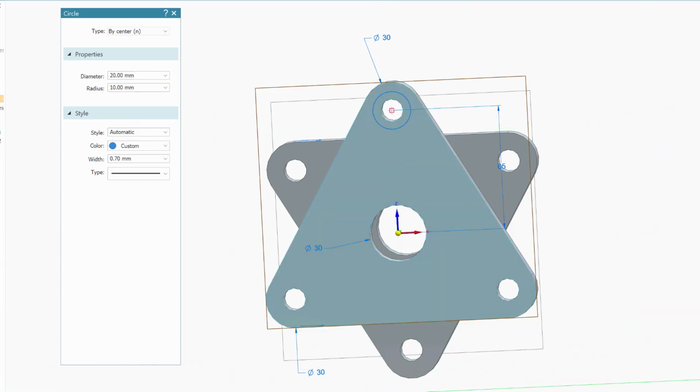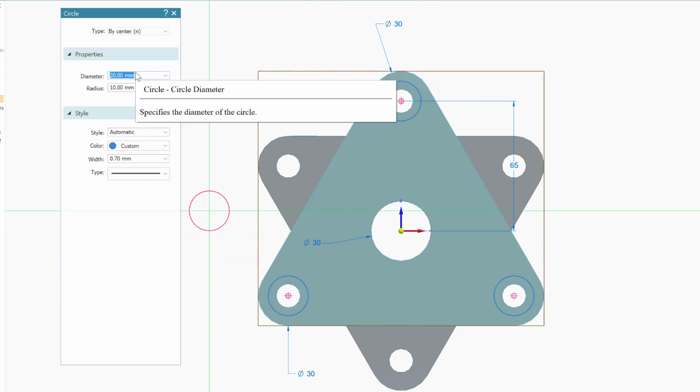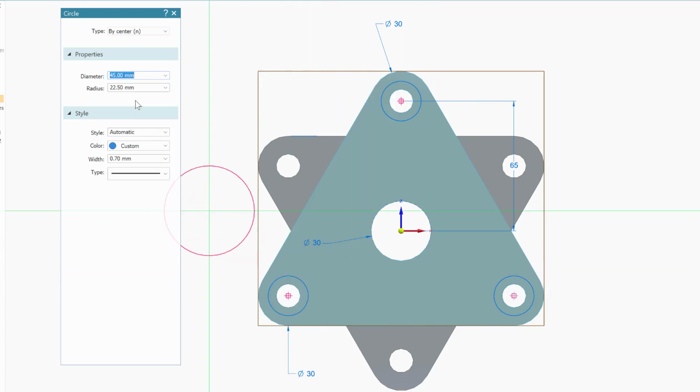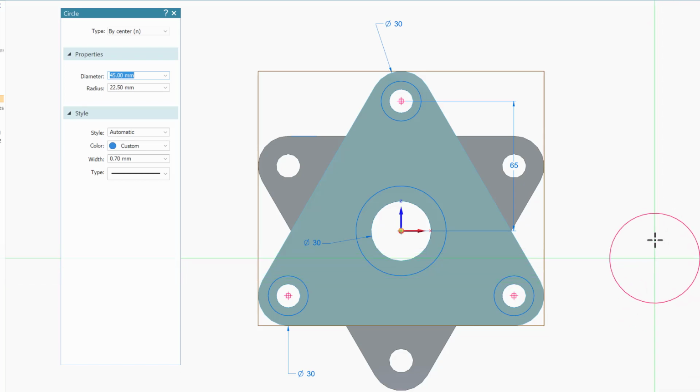Go back to the front. So highlight, touch the edge of the smaller circle. When concentric, I'm going to click. Touch the edge, you reveal the center. When it is concentric, you click. The other thing also, I'm going to change the dimension from 20 to 45 diameter, and you come to the center, you highlight the edge here for the bigger circle, and come to the center. And you click. Okay, so now I was able to do that. Okay, now can we do the other thing? We can do the other thing.